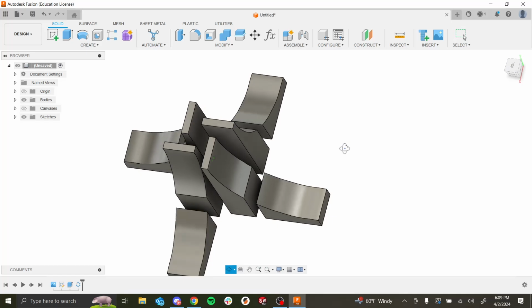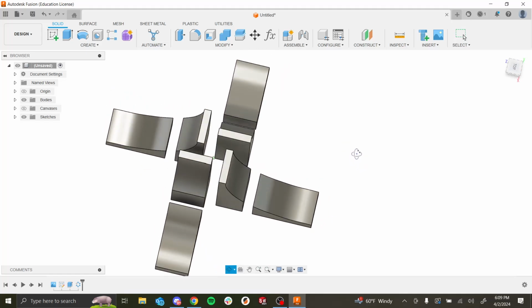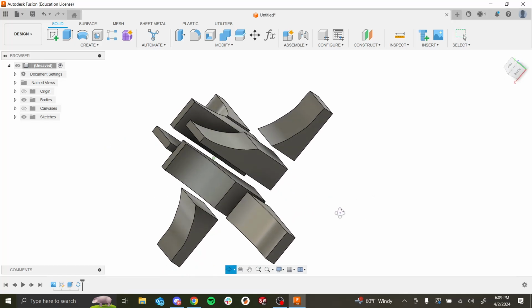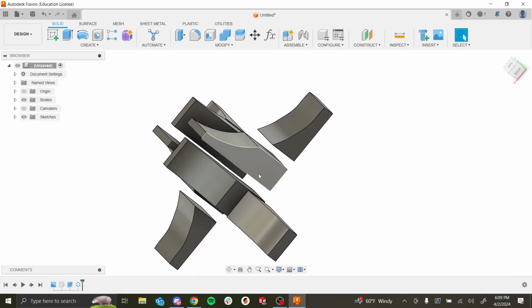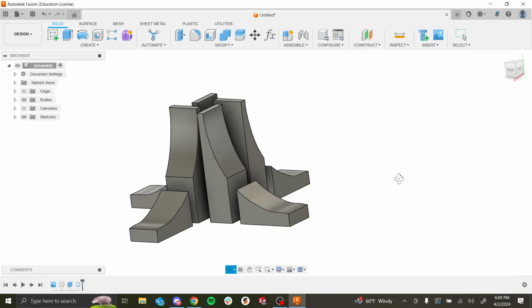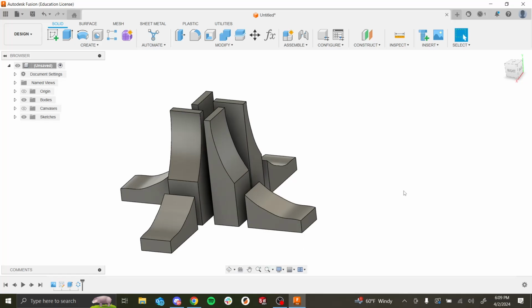So you'll see that the engineering fountain doesn't look like it should, and that's because of the way we extruded it, right? We extruded it to one side, and you're revolving it around the origin, or which axis? The y-axis. Because you're revolving something that's protruding out from the y-axis, it'll look kind of strange, right? This is not really what we're after, but there's a really easy way to fix that. Again, it's really nice that we can go back and change things.